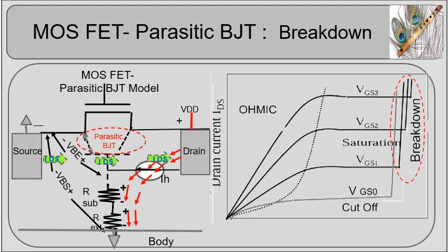As shown in the figure, the source, substrate and drain regions of a MOSFET create a parasitic BJT structure. Reverse biased drain creates a depletion region, through which the drain current flows. As the drain voltage is increased, the drain carriers get accelerated and acquire high kinetic energy, and are called hot electrons. The gate voltage deflects some of the hot electrons towards the gate oxide, where they get trapped, degrade the gate oxide and reduce gate capacitance.